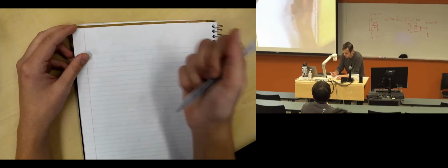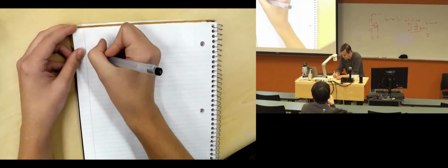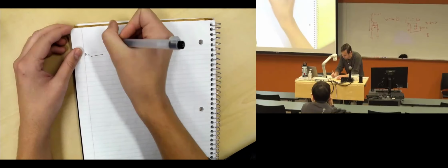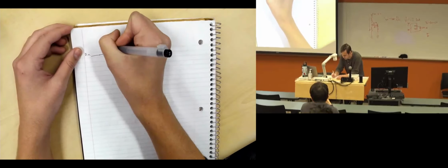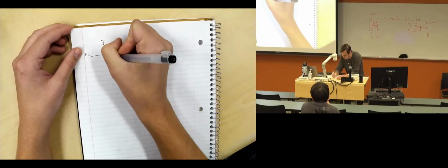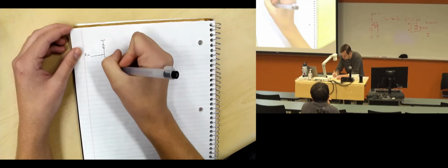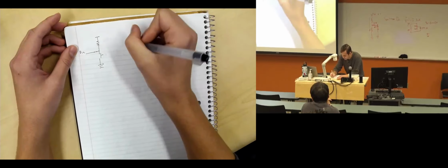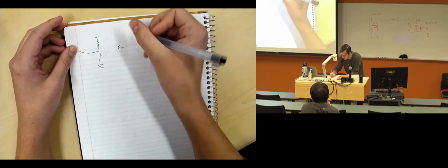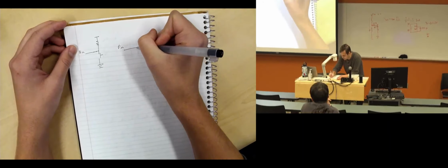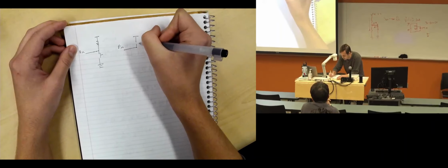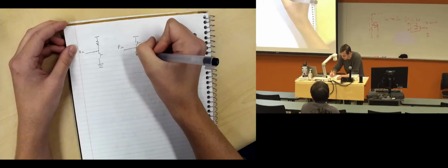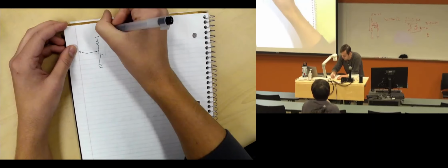Okay, so we have our pin, our CPU pin, right? And then we have our voltage source, and we have a resistor, and then we have our button, and then we have ground, right? So this is one configuration. That's a pull-up resistor. We'll get into why that is in a second. We have our switch here, our voltage, and then we have a resistor here, okay?